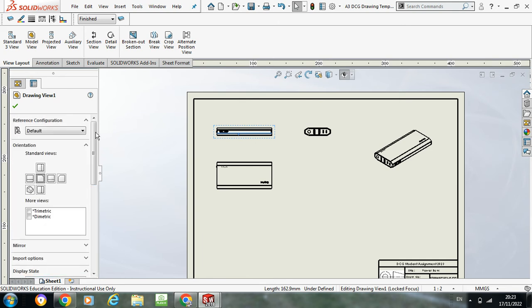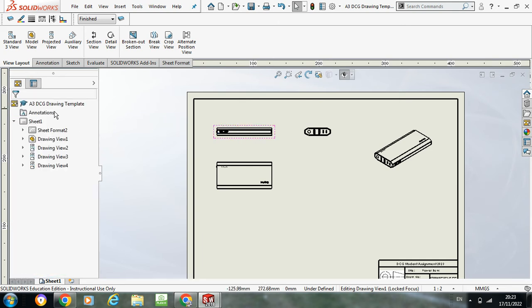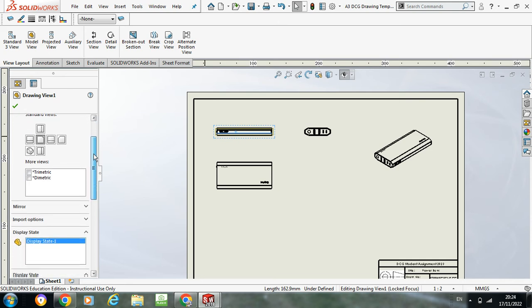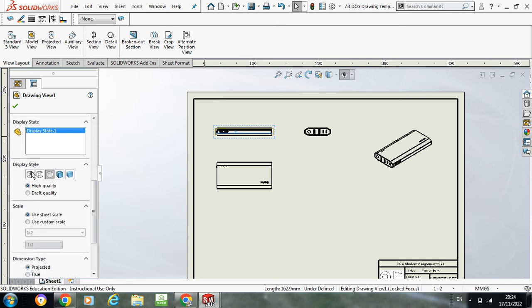Now you've got a couple of render tools here, okay. Once again, options here, but if I click on the actual icon, or sorry, of the elevation view of it, come over here to my window. Now I've got display style, I can put it into color, and you'll notice that it's all going to change here as well. Okay. Now usually for the orthographic views, I would advise, you don't have to, but I would advise maybe that you keep them in normal here. Okay. This kind of quality. If you want to put in hidden detail, you can pop it in.